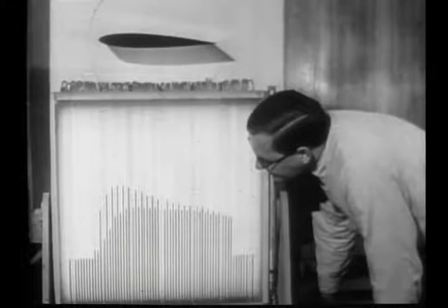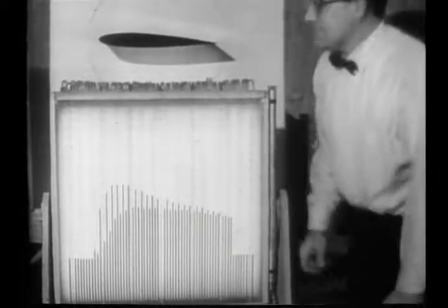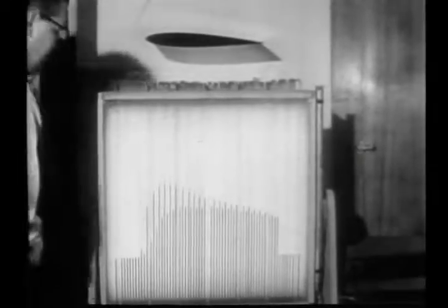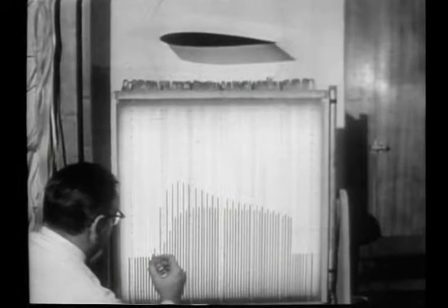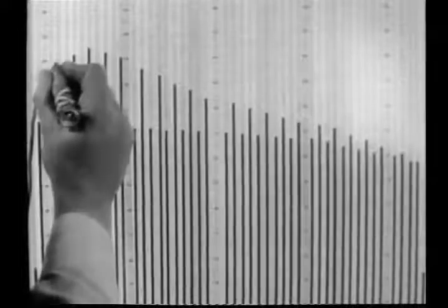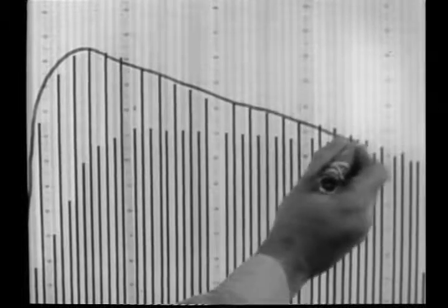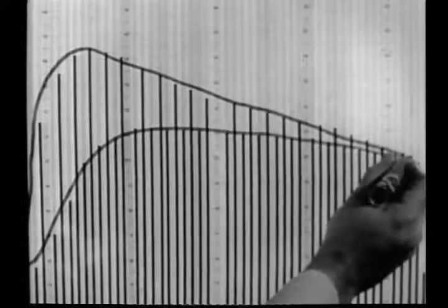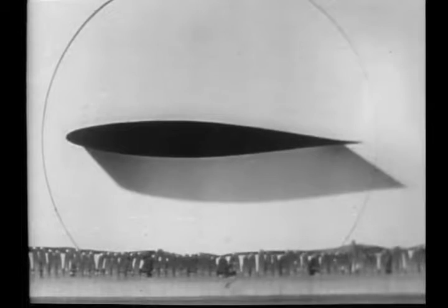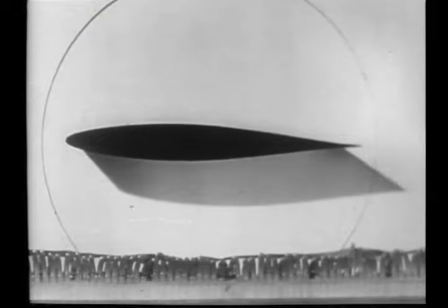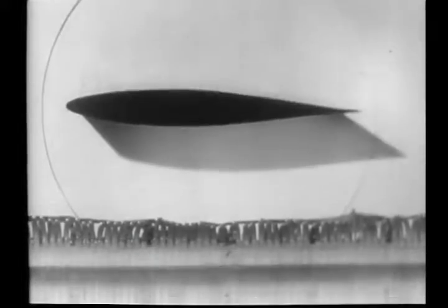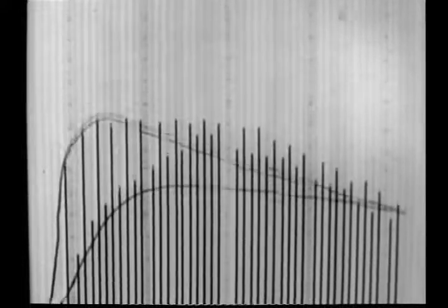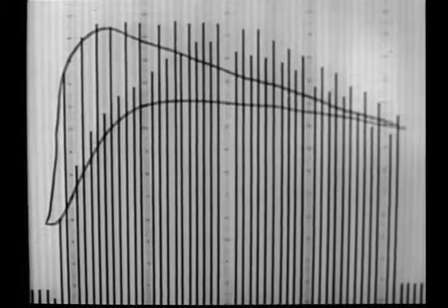For a given lift, we get a greater length of laminar flow by modifying the pressure distribution through a change in the airfoil shape. To demonstrate this, the lift of this profile at this angle of attack will be indicated by the area of this pattern drawn on the manometer. Here is another airfoil, adjusted to give the same lift. It has the same maximum thickness as the previous one, but further aft, close to the mid-chord point. As a result, at low angles of attack, the extent of the favorable pressure gradient over the upper surface is increased well beyond that of the previous case.